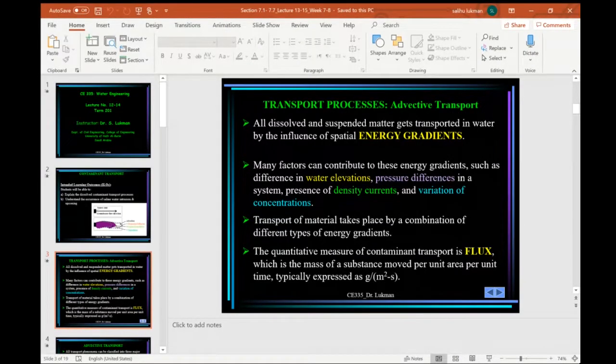Deionized water is obtained using what is called reverse osmosis, the RO system. That system completely removes all dissolved minerals, all dissolved salts in the water, so that only H2O can pass through. It has tiny filter fibers that only water can pass through. Any dissolved mineral cannot pass through it. So you have distilled water, you have deionized water. All these are pure H2O, pure water, free of any contaminant.